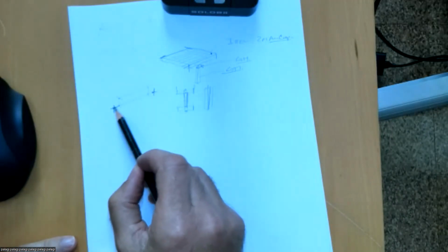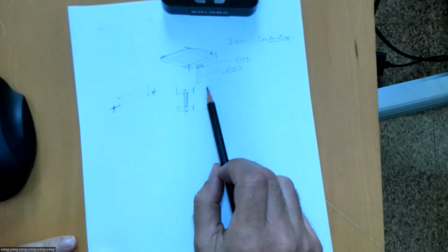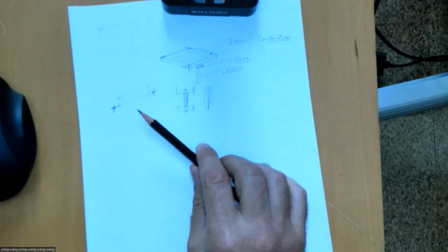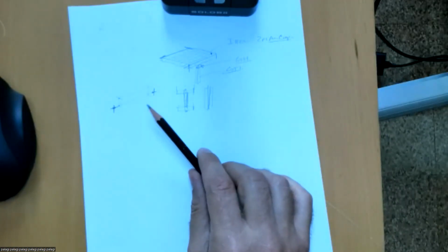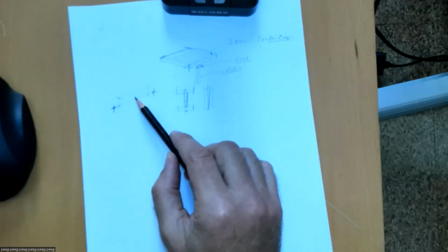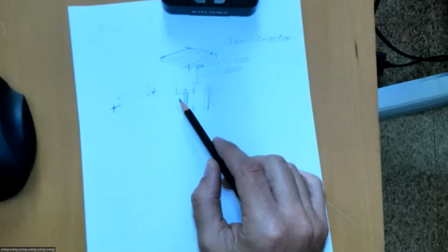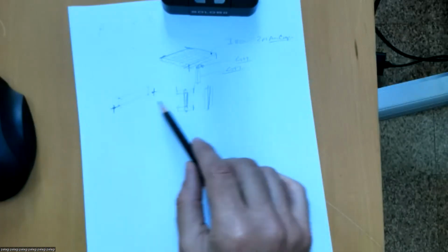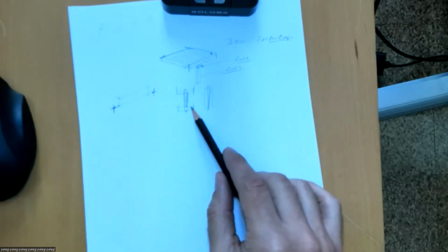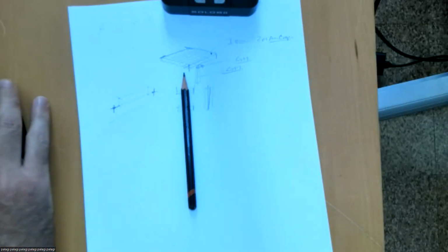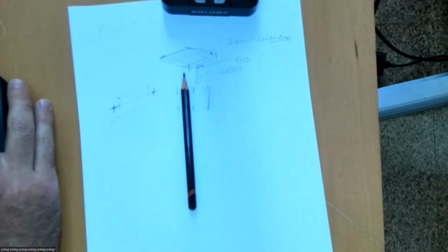Okay, we are going to do the offset the same way again. I'm going to start from the beginning again. If I was doing this just on my own, I would probably grab this original box beam and make a version of it, so save it as something else and then give it some other parameters. But I'm going to start from the beginning as if I hadn't made this other one. Okay, so that's the first thing we're going to do. Let's do this generic model. Switch to share screen.